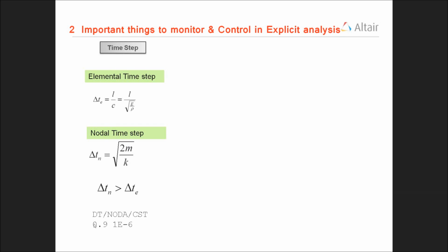And we insist the solver to run with one particular time step. You may relate this number, it is 1e-6, 1 microsecond. You might have done your meshing with a particular time step, so here I'm putting the same number. I'm not getting into the concept of time step.